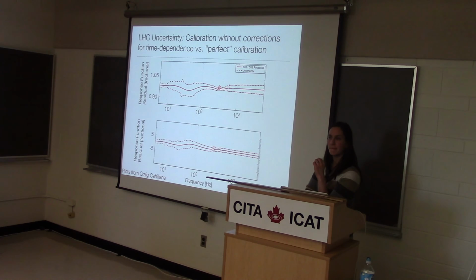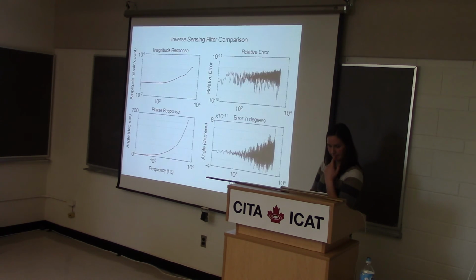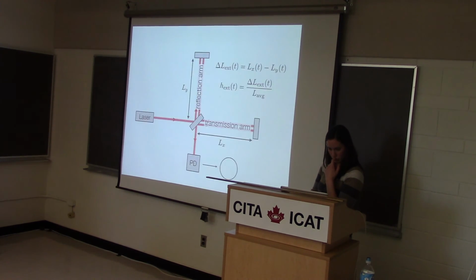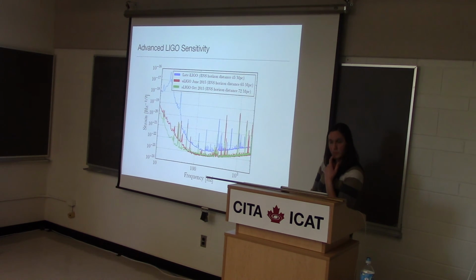So at the outset, you showed this strain sensitivity curve. How much does that change with time? You showed us the error in calibration, which is like 5%. Does that mean the green line there will vary, say, 5%? Oh, well, the green line actually varies much more than that. It's just our ability to know where the green line is that is within 5% in magnitude.